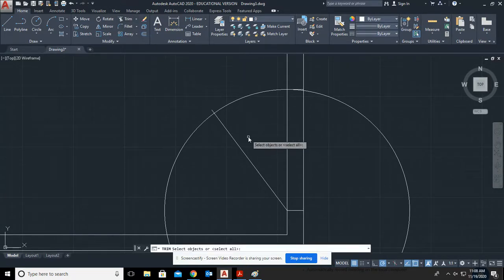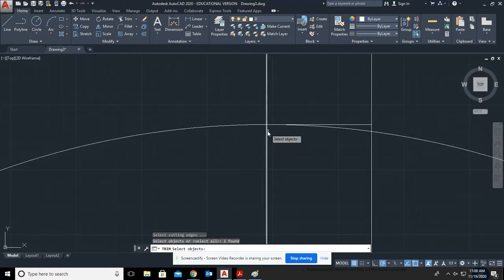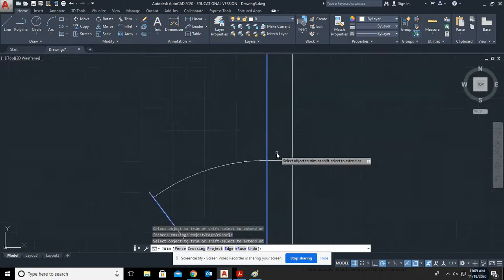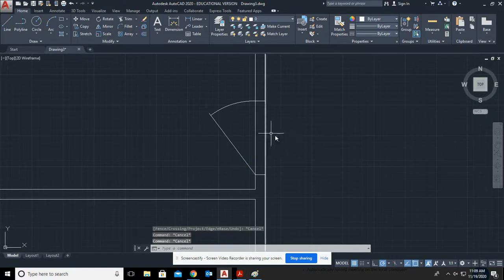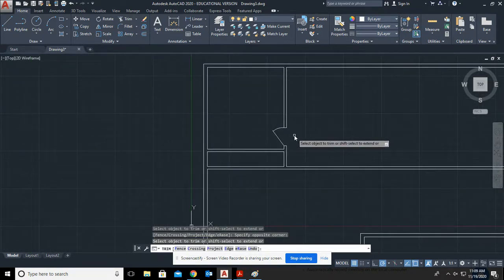Now for trimming, we're going to trim to here. There. Now we'll trim again, enter, and flip that up. So there's a door, right? 6 inches out, that's a 30-inch or 2 foot 6 wide door. Pretty simple. So hopefully you can copy this. If you want to just copy this one and move it around or rotate it or mirror it, make it fit wherever, that's fine. But it's the same procedure everywhere.